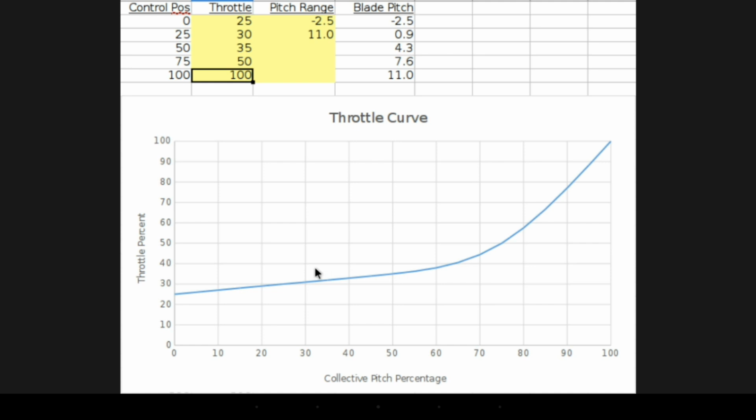The power changes quite dramatically with gas engines from idle speed up to about 50% throttle opening, and the power output changes less dramatically from 50% throttle opening to 100% throttle opening. So we want a throttle change that is less in the range where we get up to 50% throttle opening, and then we want to increase the opening on that throttle way quicker.